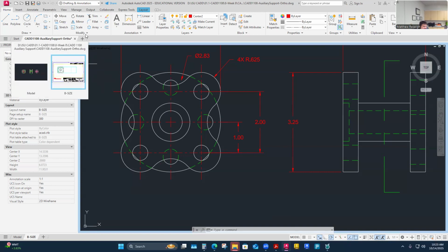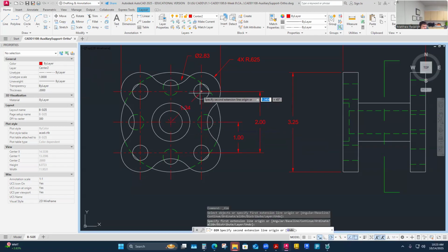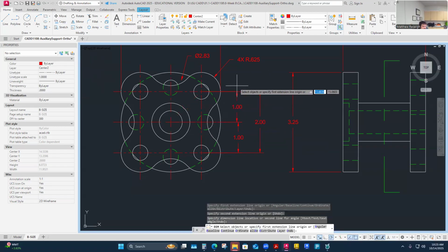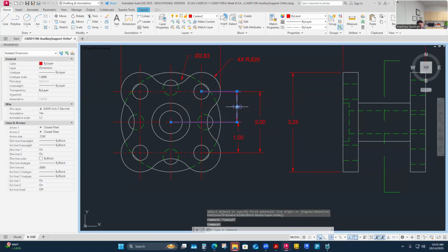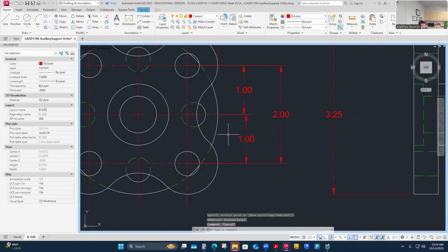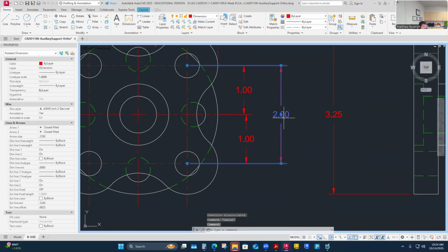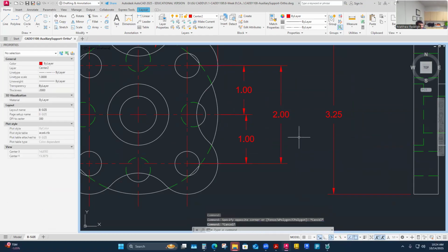It's not a double dimension here. If I actually put this one to here, it's definitely different features that I'm calling out here. I'll pull this back to the object edge as well. And this might be a better dimensioning. So I'm 1 inch off of both centers, and this maybe would become a reference or even dropped. If I left it, I'd probably call it a reference dimension and put it in parentheses.